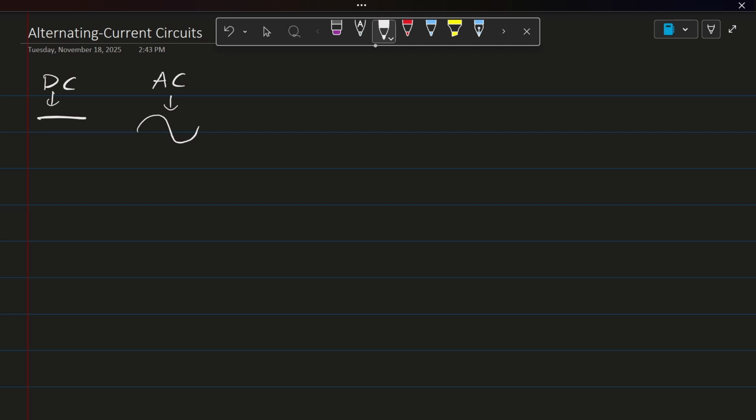So what are the ways for us to describe an AC circuit? The most general idea is by using sine waves, because if you have already taken calculus or maybe even differential equations or even signals, you know something about the Fourier series, in which you could construct any periodic function in terms of sines as well as cosines. So here, I'll just describe this to be cosine omega t. Or, you know what, here I'll just describe this as sine omega t plus phi.